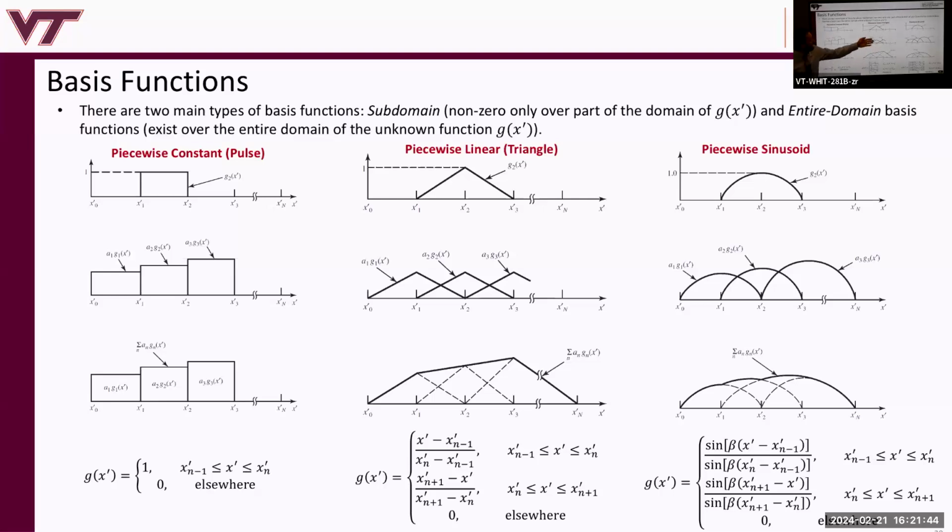These are the 2-dimensional equivalent of what are called the Rao-Wilton-Glisson basis functions, which have linear basis functions over triangular domains. That allows you to model 3-dimensional arbitrarily shaped structures. Anyway, they're defined like this.